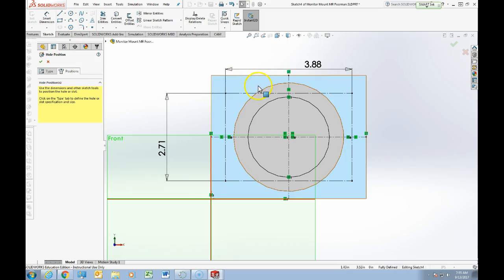So now what I'm going to do is, we've probably lost track of the fact that we're trying to place where those threaded features need to go. Coming up here, and I'm clicking back on, now I've got nothing else selected. Point. So now that I do this, that point icon comes back up, and now that I'm sketching points in the whole wizard, I'm just going to drop those points at the corners of that rectangle. All right.